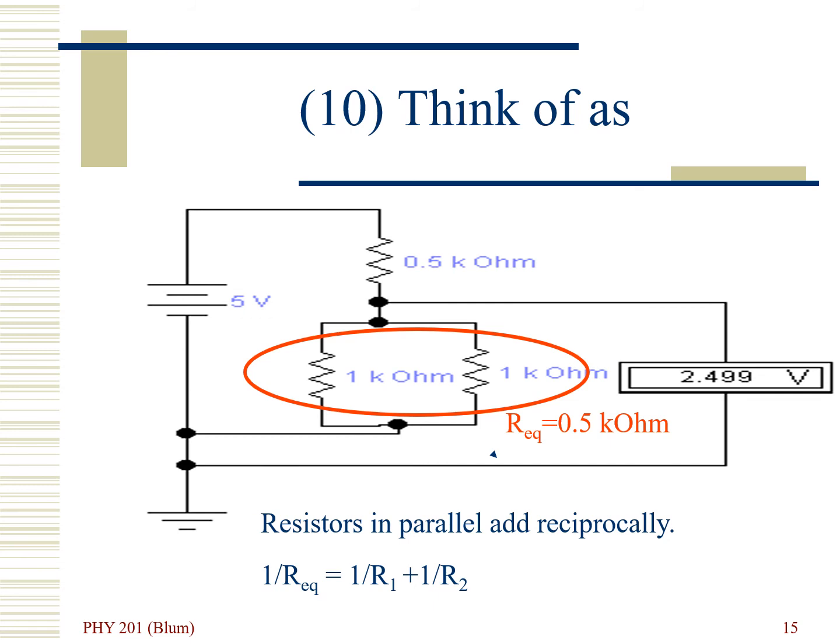So in order to go from the high end of the battery to the low end of the battery, we first pass through that half kilo ohm that was connected to switch B, and then we connect to these 2 in parallel, whose equivalent is also a half kilo ohm. So at that halfway mark, we are indeed at halfway. We are using up half the voltage for the first part and half the voltage for the second part, and the dividing voltage is 2.5, half of our maximum voltage.